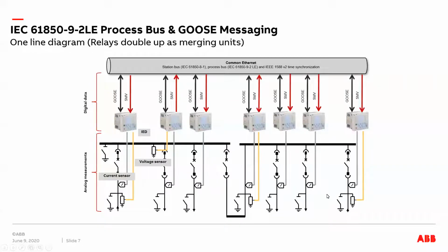And so these 2 main relays have the line PTs, or sorry, I should not say PTs, it's a sensor, the line voltage sensor connected to it. So it has a line voltage on the main relays. Now, from the bus voltage standpoint, on the bus A, you have a voltage sensor, which is connected to this feeder relay here. Okay, so this is the bus voltage sensor. And its respective current sensor is connected to the relay as well.